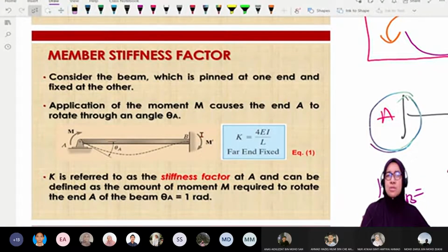Why do we need to do that? Because shear force and bending moment are actually internal forces in beams and frames, and in truss we calculate member forces. Member forces are internal forces in truss. So why do we need these internal forces? Because to calculate displacement, we need to know internal forces. And of course, analysis of determinate structures is quite straightforward, and quite short as well.